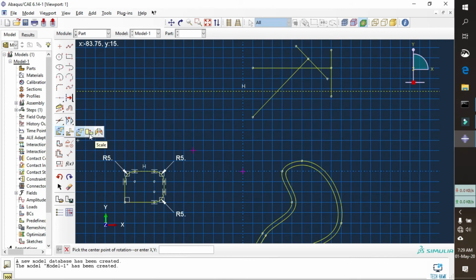the scale. I want to inform you something. To scale any objects, just use the scale tool from the toolbox to enlarge or reduce the sketcher objects. So if you want to enlarge or reduce the scales of line, arc, circles, ellipse, fillets or spline or any specified points, just click here.